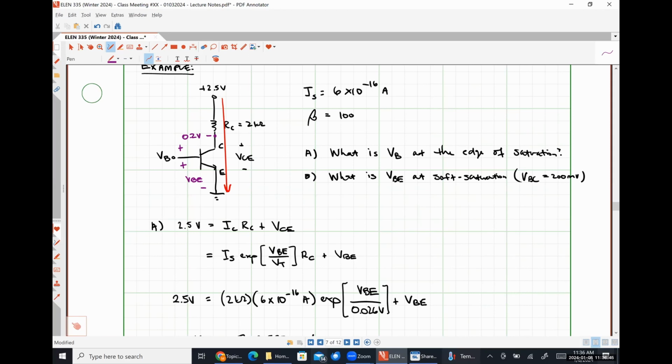And now I'm going to do a whole new analysis where I do KVL along the left-hand side of the screen. Oh, scary. So I'm literally just doing this path, which will allow me to calculate VBE when we're in soft saturation without ever having to look at that completely and utterly asinine and useless model that we're supposed to use when we're in saturation mode.